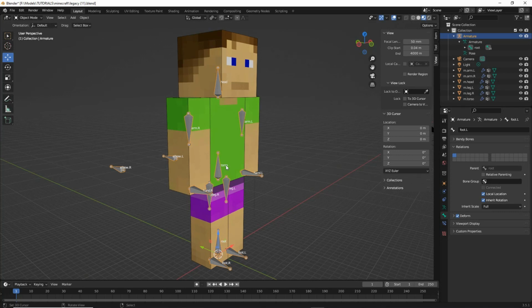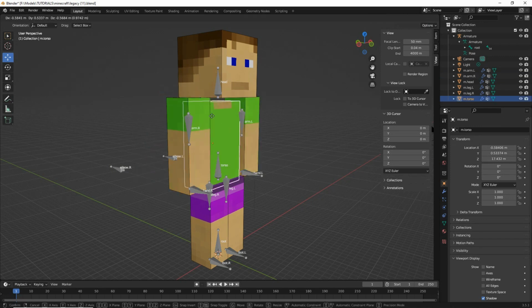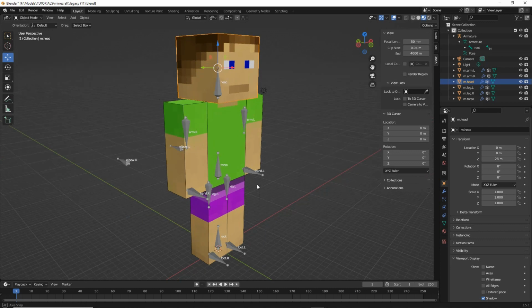And there are two ways that we can do this cheaply. And this is the key. We're doing this as a low-cost way to create the effect of the outline around the character. So the first one is to literally duplicate the meshes. So we duplicate each mesh, we invert them, and then assign a black material. What that will do is create the effect of an outline, because we're essentially looking at an inverted mesh. Again, it'll all make sense once we actually do it.